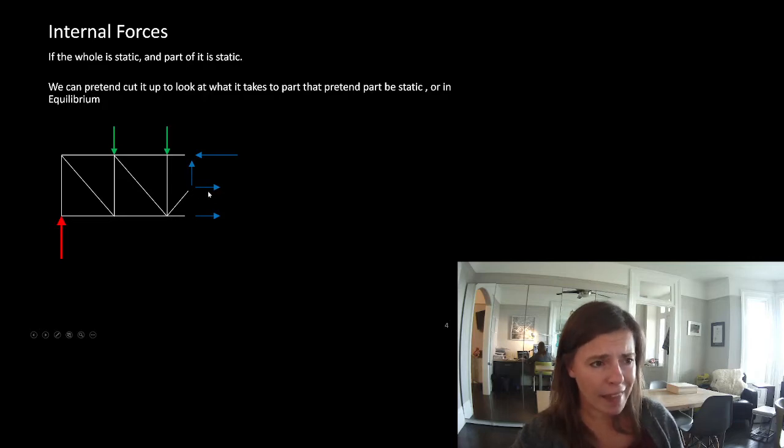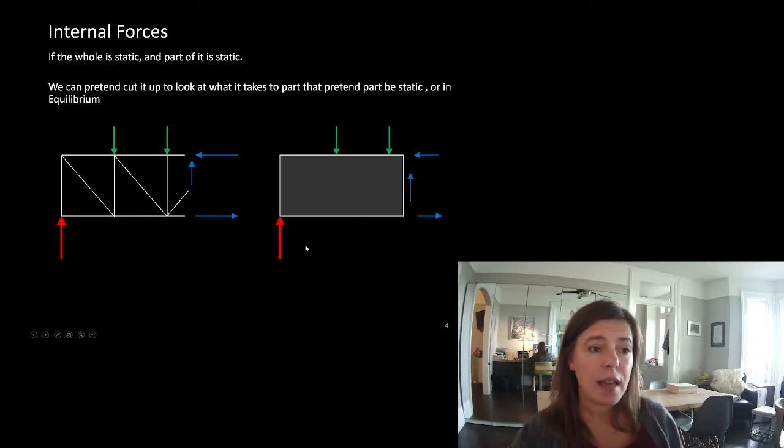So really then, this is in the same plane as this. So we can add them linearly. So we can just rewrite it like that. Well, we know that if we have a force going in that direction and a force going in that direction that are equal and opposite, we have a couple. So we know that we can rewrite this as a moment.